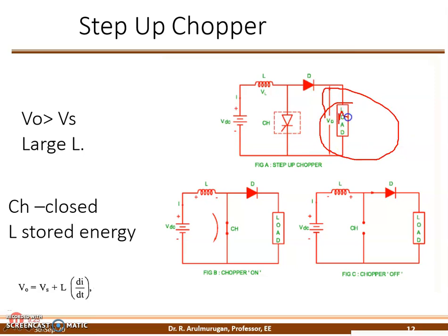So if I connect it, during the mode 1 and mode 2 conditions, what will happen? My motor output voltage is 100 volts and the input voltage is 50 volts. Which is higher? Output is higher. Because of the motor load, output is higher. So now regeneration is possible.